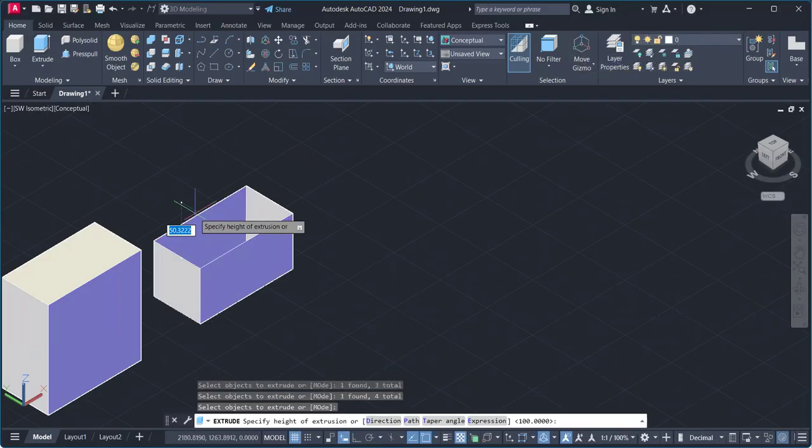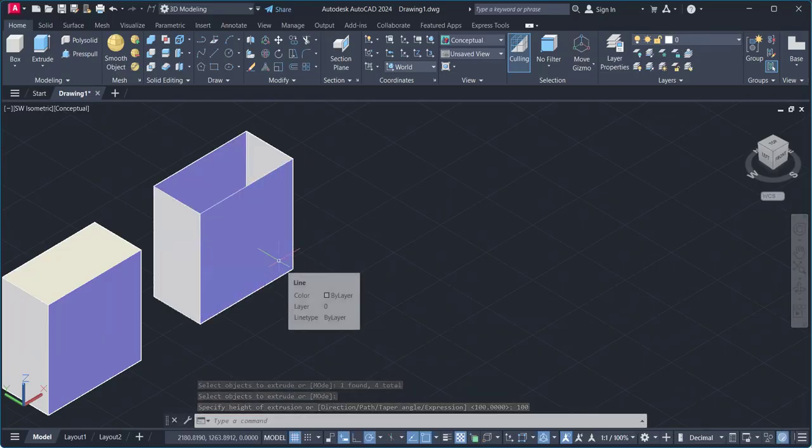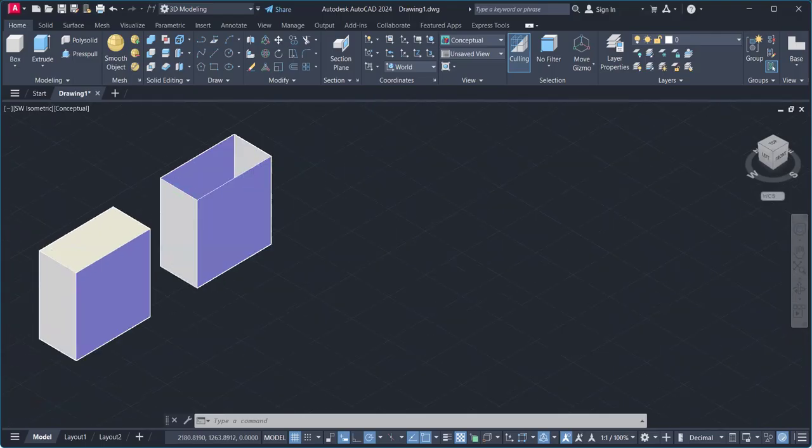For the extrude command, you are shown something like a wall. Okay. This just extrudes only your line, only your object. Okay, if you have a closed object, a single object made by use of the polygon, then the extrude will convert this into solid form. If you make it by use of simple lines, then only the lines will be converted, only the width and height of the lines, also on all the parts. Okay. This way, you can only create here.